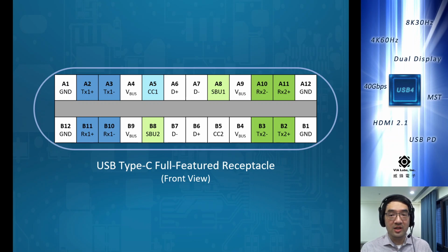In theory, we actually are able to wire up all 4 lanes of the Type-C connector to support DisplayPort, but then we lose SuperSpeed USB functionality. And as USB guys, we think that's a very sad thing.